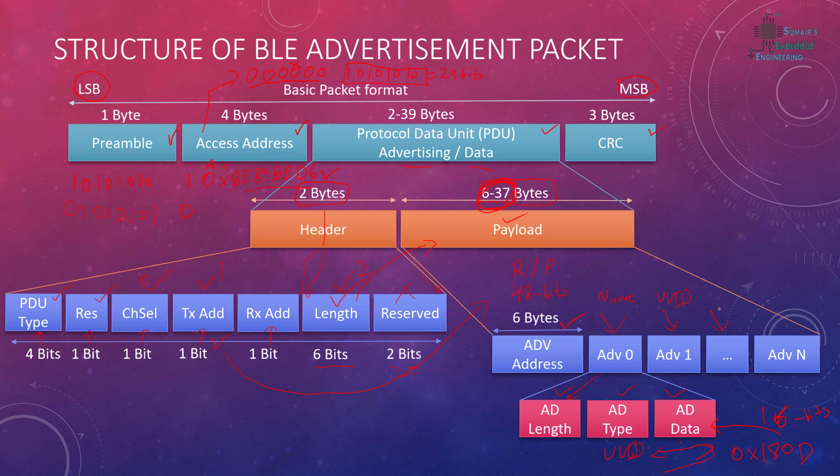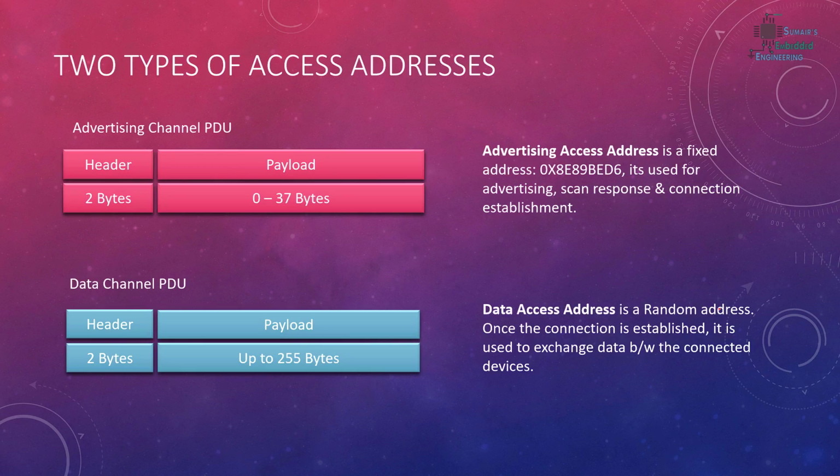We can add many things in the advertisement. Basically we have a limited packet size, so we have to make sure we are transmitting the data which is necessary in the advertisement. If it's not required, you are not bound to transmit every single thing in the advertisement packet. It's all up to you and your application. Let's move to the next.